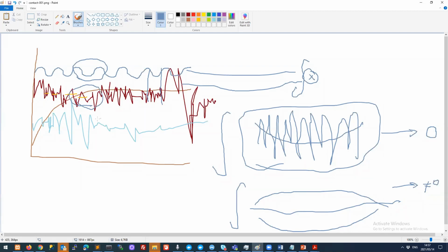So when we multiply this cos function by this measurement function and integrate in time, it gives us back one number, and the size of that number tells us how often that function had this frequency, right? Remember, when the function is not similar to this frequency, the result is close to 0. So the values where the frequencies are not the same will be approximately 0, whereas the values that are similar in frequency will tend to survive that integration.